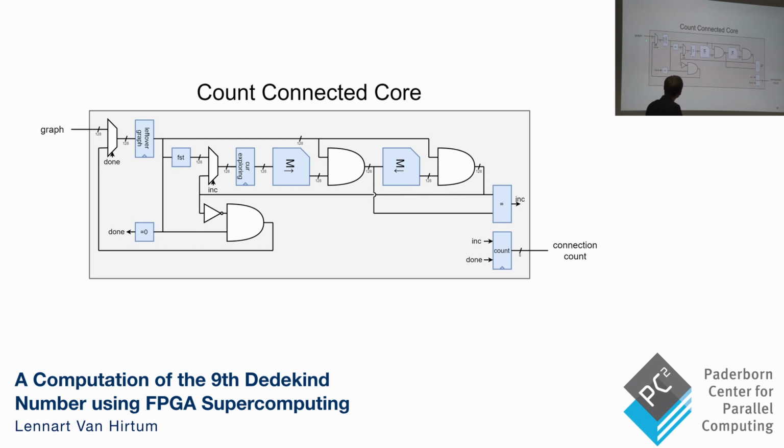So again, the same algorithm. A graph comes in. We store it in this register. We grab a random node from it, and we store it in the register that we're currently exploring. We do this monotonized up, exploring up. We do this monotonized down, we explore down. And we store it back in the current extending register. And we keep looping through here until there is no change. If there is no change, we remove our currently exploring area from the current graph. We store the new graph in our graph, and we pick a new seed. And we keep doing that until we're done.